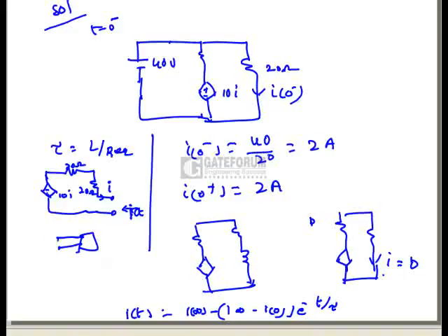So in that case, what we do, you just apply a voltage here and just find out the current here. Then V by I is nothing but an impedance of the network. In this manner, we are finding the unknown impedance of this network. So I am applying here a voltage of 10 volts. Intentionally I am applying 10 volts here. Now if you apply KVL here, minus 10I plus 30 into I plus 20 into I plus 10 equal to 0. Then what we will get here, that means 40I equal to 10.